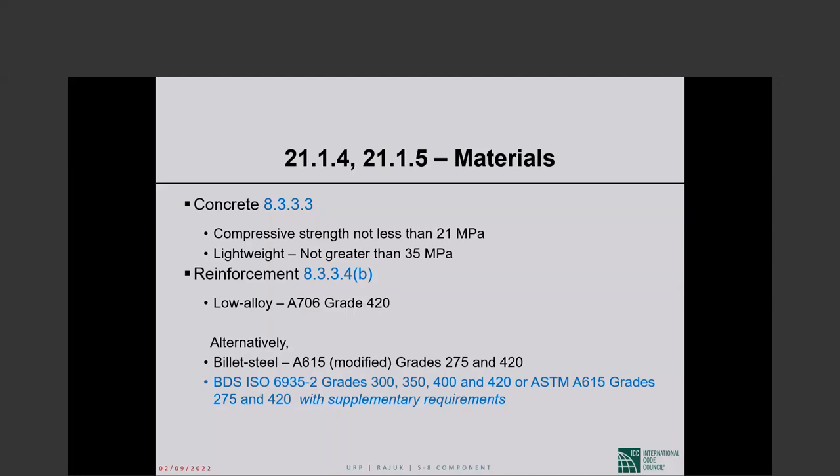Okay, concrete, normal weight concrete, there is a minimum strength of 21 MPa, which is slightly higher than the 17, I think, which is the absolute minimum anywhere. That I don't know is anything to discuss. Concrete of that strength is not difficult to find anywhere anymore. The more important thing is ACI 318 is probably the only major code left that does not have